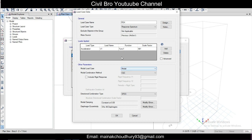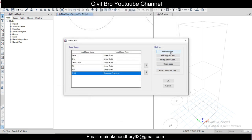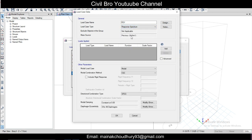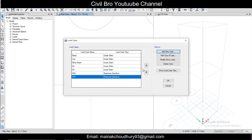and this is in the x direction, and just click on OK. Another one, we will add a new case, and this will be RSY, and this will be in response spectrum. Click on add, and this will be U2, that is in the y direction, and the scale factor which we previously calculated, 981, just add here and click on OK. So the response spectrum has been added, and then just click on OK,